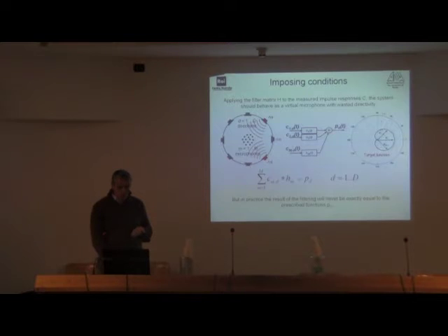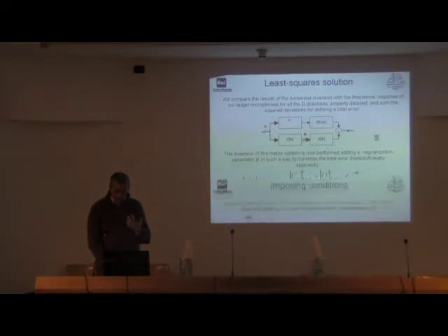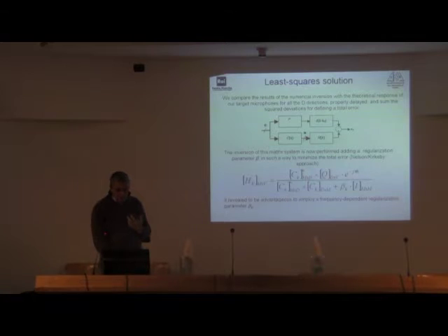We impose that the filter applied to the measured impulse response produce the prescribed directivity function of your target microphone. We get a system, which is the one below here, where the filters applied to the measured data should be identical to the prescribed directivity pattern plus some modelization delay. At the end of the long history, we get this equation which gives you the matrix of filters.